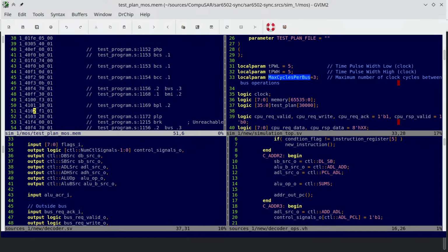Okay, what happened here? Why did branch plus fail us? So branch plus is at 4104 01, and it has a relative jump of F1. Now, F1 is a negative number, which in itself is not a problem, because we're doing 8-bit arithmetic. F1 would decrease the value of the program counter. So that's fine.